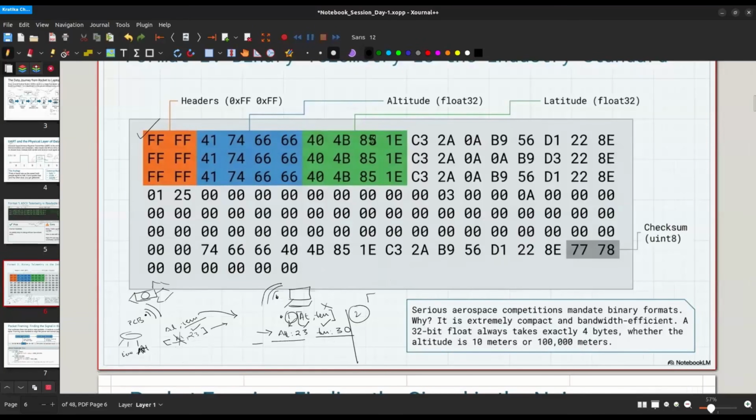Okay, you just say that instead of just receiving the first value and giving it as altitude and the second value and giving it as temperature, whenever I encounter FF, this header can be of any kind, 0F, 0x, anything else. When I encounter something like FF, I'm going to say that this is a new packet, and after this I'm going to index every value just after receiving the FF.